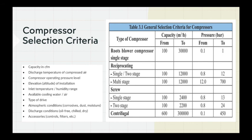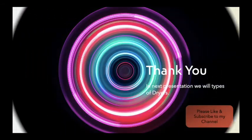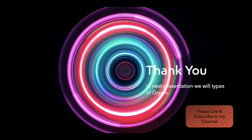Further, as seen from this table, as I have explained earlier also, centrifugal compressors are normally suited where the flow requirement is high, that is, centrifugal compressors range from 600 CFM to 30,000 CFM, and the reciprocating or screw compressors, or I would say rotary compressors, are characterized by the high pressure requirement. So that's all on the types of compressor.